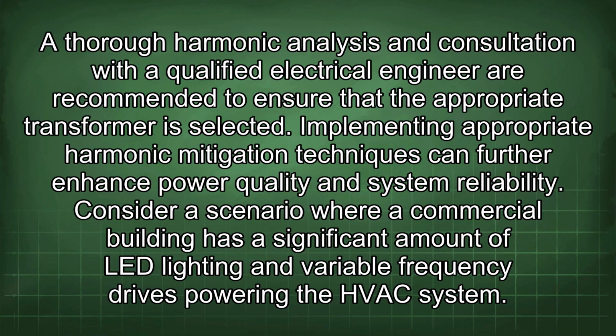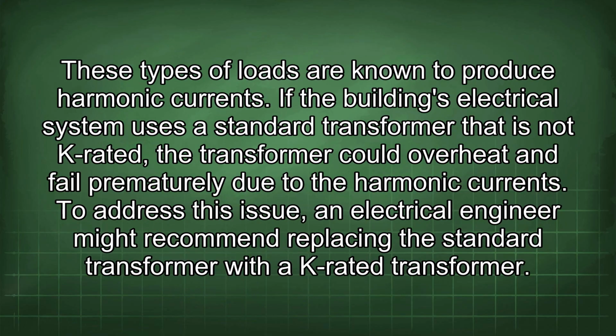Consider a scenario where a commercial building has a significant amount of LED lighting and variable frequency drives powering the HVAC system. These types of loads are known to produce harmonic currents.